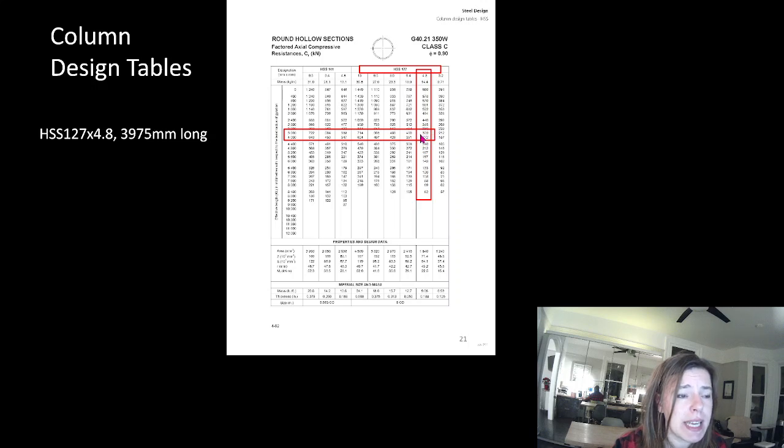So we can see our possible values here. We're somewhere in between here is our compressive resistance. Look at this. Here, as we get tall enough, there are no published values because that's where KL divided by r is greater than 200. So we have no compressive resistance here. Even though we could calculate and have some compressive resistance, we say there is no compressive resistance.